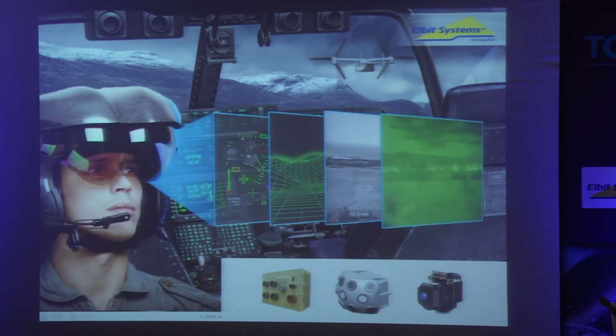allowing them to see. So in our system, we have mounted on the aircraft several sensors, active and passive sensors, which have a good vision under these conditions. And then we have a processing unit on the aircraft that collects all the data together and meshes it up to create a 3D model with texture applied onto it. Then we render this model from the line of sight of the pilot and project it onto his or her head-up display. So when the pilot looks outside the window, they actually see our synthetic vision overlaying the real scene, which they can't really see.